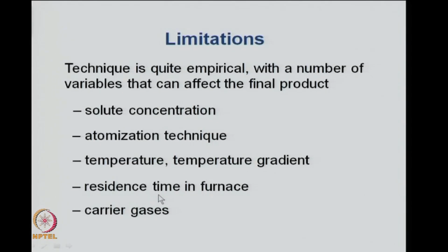That means how long these droplets are residing or moving in the furnace. So, that will depend on the length of the furnace. If you modify the length of the furnace, the residence time of the droplets in the furnace will change, and that will affect the size of the particles and the distribution of particles in the product.